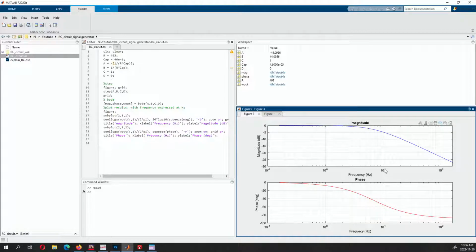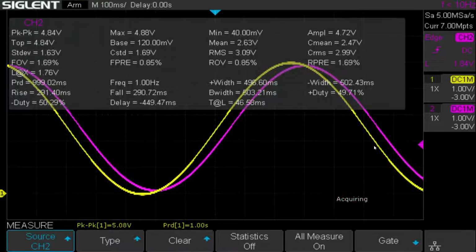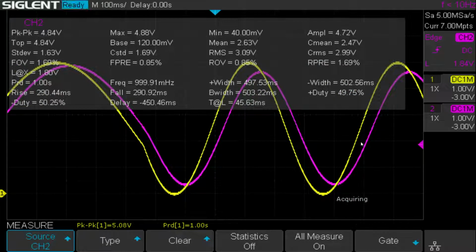What if I go to 10 hertz, and then we should see the amplitude drastically decreasing. And if I go to 100 hertz, it's going to be almost flat. So you almost have a low pass filter, because if the frequency keeps increasing, it's not going to respond after that. So let me increase the frequency. So it's going to be 1 hertz. This is going to be 2 hertz. This is going to be 3 hertz.